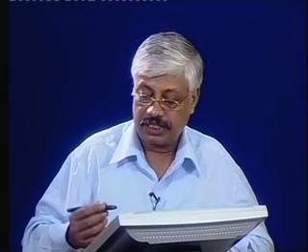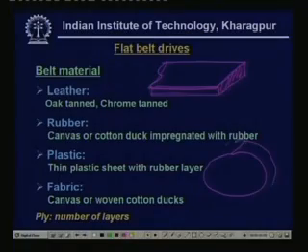In the flat belt drive also, one has to decide upon the belt length from the calculation or the equations that you have just seen. Once he or she finalizes the length of the belt, that much length of the belt of a given specification can be cut and joined together to form a belt. So, one situation that comes into the picture is that this belt requires a joint somewhere.